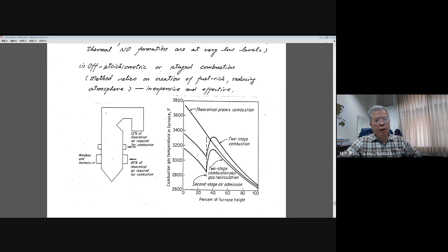At this point, you apply an additional 50% theoretical air in this region. Then they start to have dim mixing, increasing the temperature in your combustion chamber up to the optimal high value. Then they will drop down continuously.